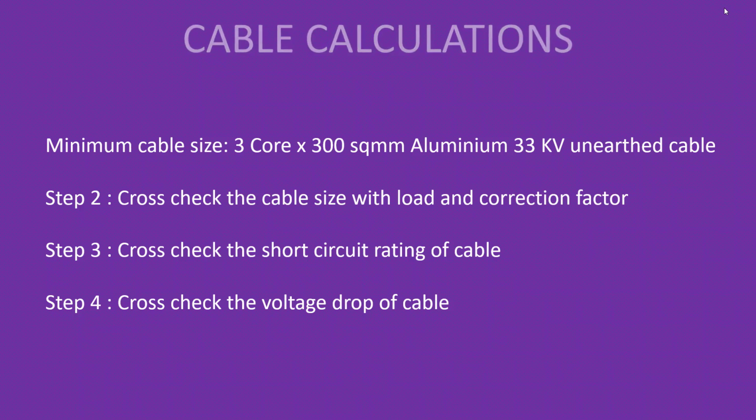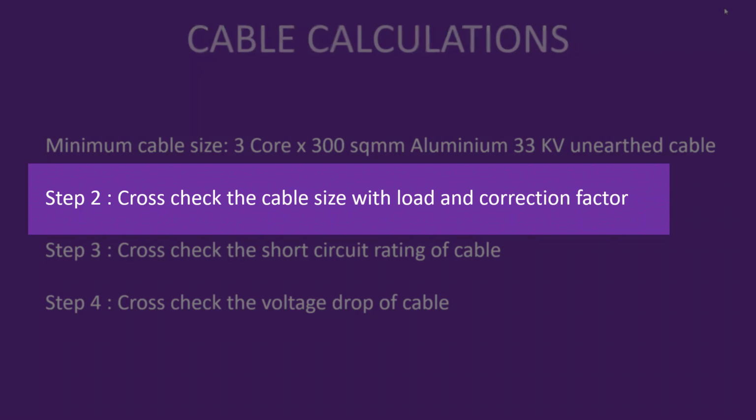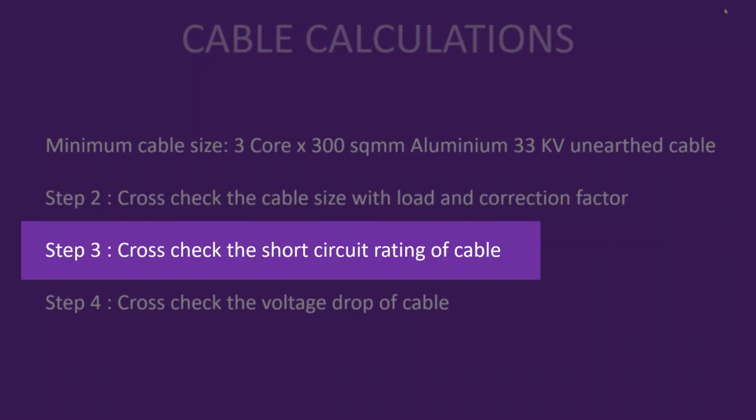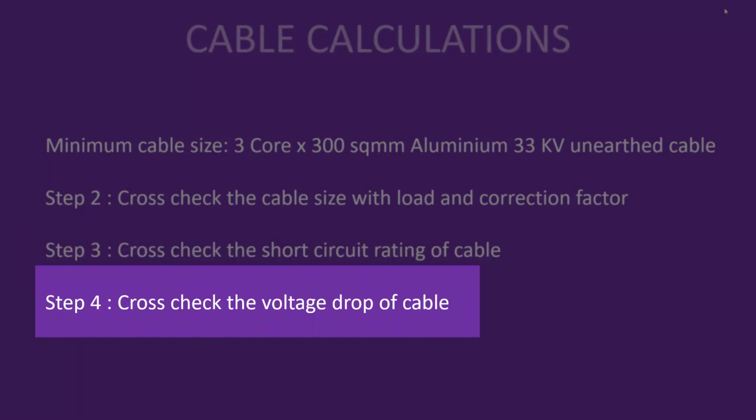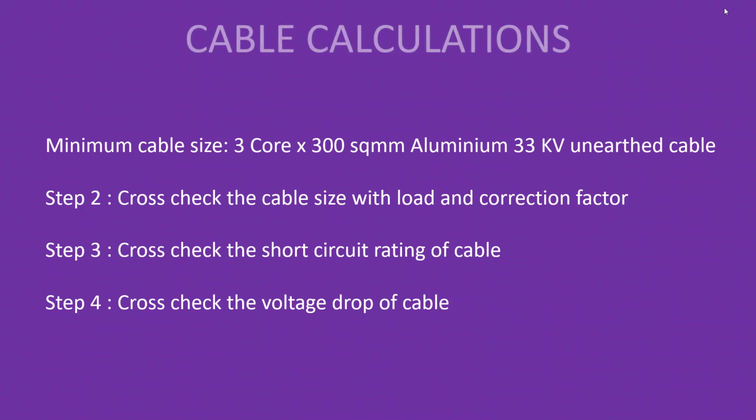Is this cable size final? No, it is not final. We have to do 3 more steps. Step 2 is cross check the cable size with load and correction factor. Step 3 is cross check the short circuit rating of the cable. Step 4 is cross check the voltage drop of the cable. I have demonstrated this in the earlier example. You can do it as an assignment.